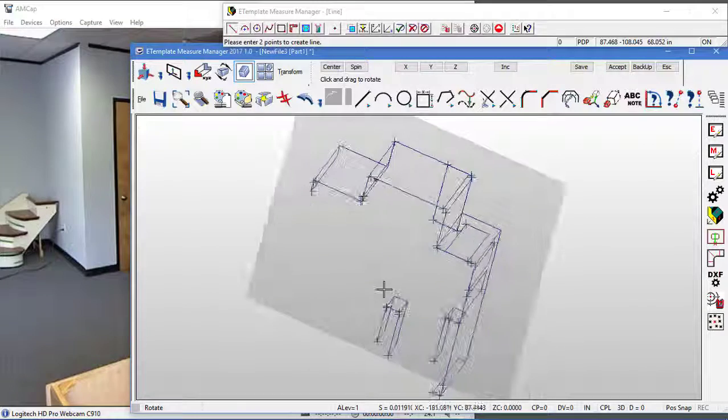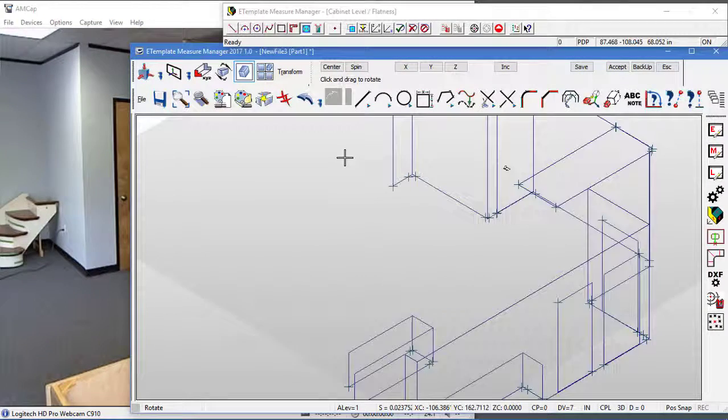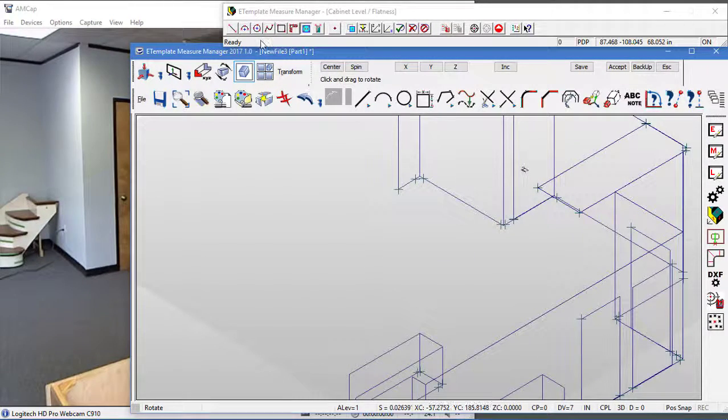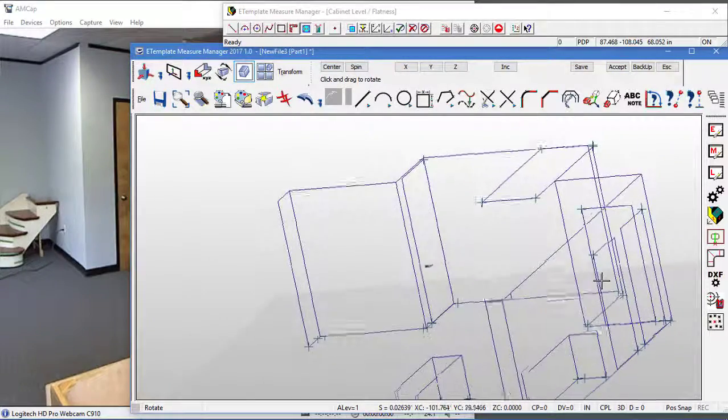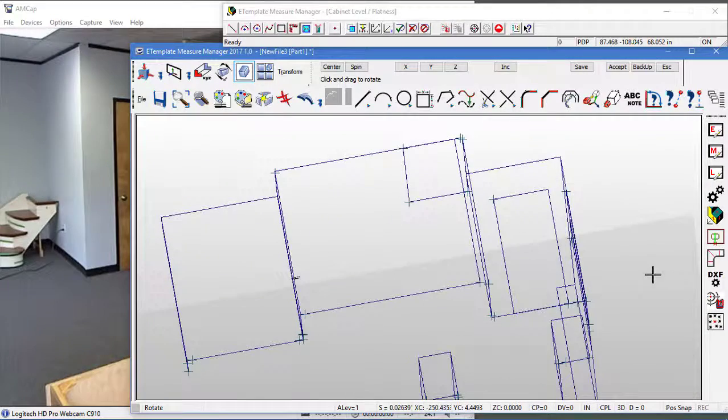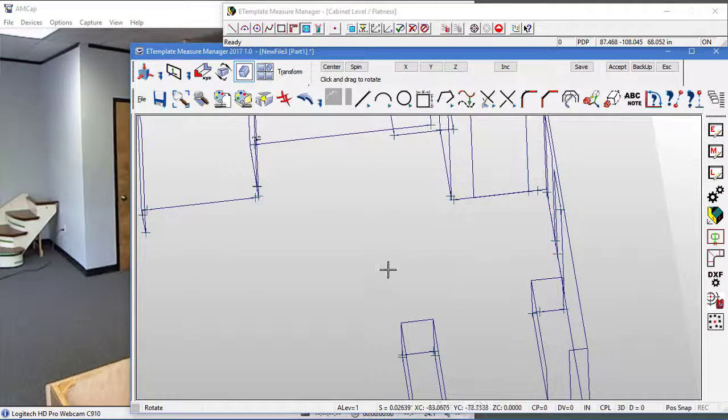It would be nice for them to know how flat this floor is down here. So I'm going to move my construction plane once again to the floor so I can do floor flatness. Now I'm going to just spin it a little bit and make sure that I've dropped it to the floor, and you can see the little gray parts on the floor. And now in the area along here and along here, I'm going to create some patterns so that if he does bring that stairway out and over, or if he just brings it straight down, that where it lands, he'll know how flat the floor is.